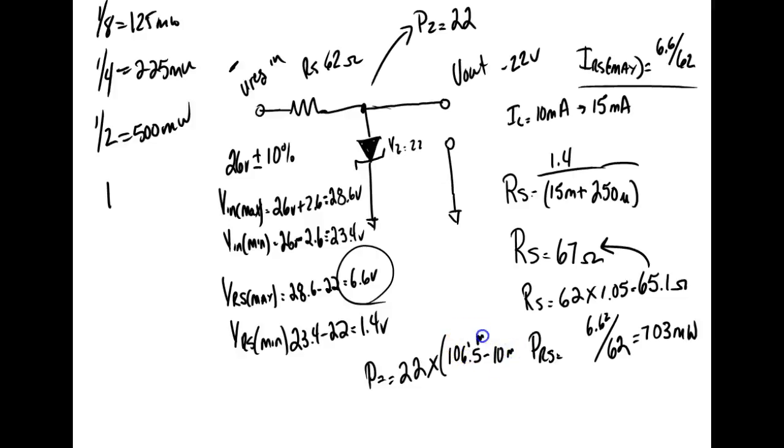And this is milli too, by the way. So a while ago we used 0, so that power supply could be unloaded. Here, if we've got a load that's pulling current all the time, then that will never be Zener current, and it will allow us to use a smaller Zener. Now, if the load ever opens up, it's going to burn your Zener up, but you know you got bigger problems anyway. So what did we come up with for PC? So what Zener did we choose?